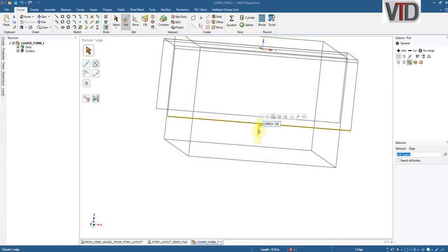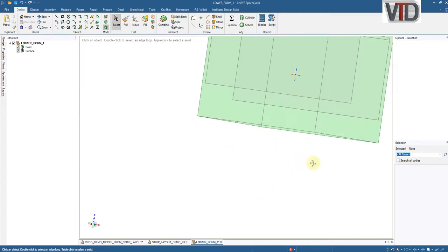3 millimeters past plus a 1/4 inch for radius plus whatever radius we're going to have on the top. We're going to have a 5 mil radius on the top. So let's do 5 millimeters here. You see how I'm putting the metric dimensions in brackets? That isolates them and converts them to inches before it does the math. And there you go. So now I've got my length of my thing.